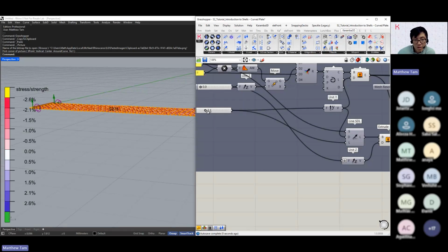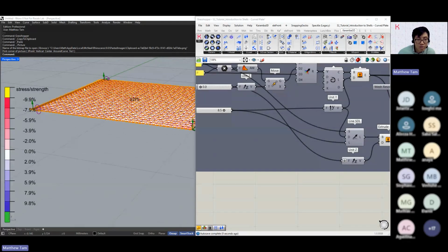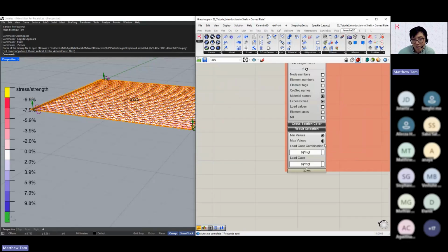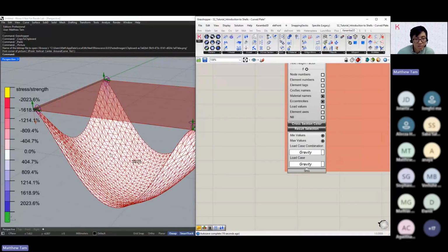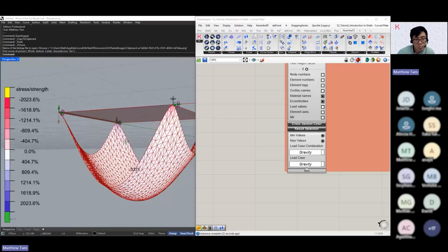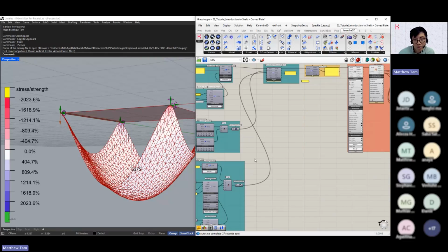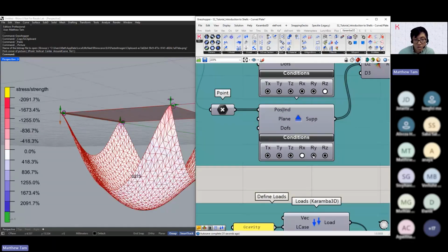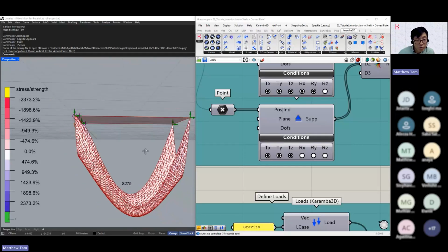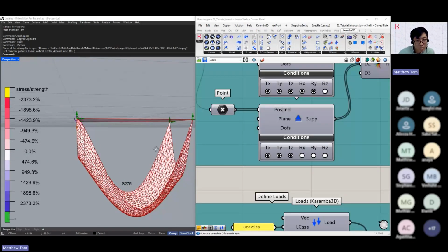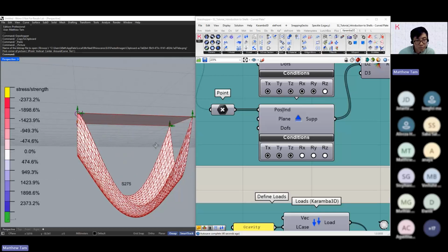And of course, this is then controlling the depth of our shell or the plate. And as I mentioned at the start, we're not analyzing it as a support along the entire length of our shell. So now if I go to the gravity load case, you will see that it starts to deform like a piece of fabric or paper where it's held at the four corners. And by releasing rotation, it also has great effects on the deformation shape, as you can see in this case.